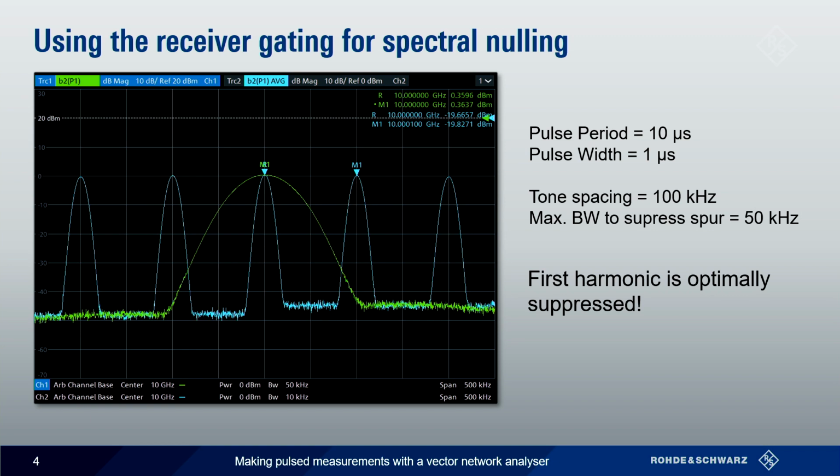So we can see each of the line spectra. The central component is the one that we want because this contains the information about the carrier frequency. And overlaid here, we can see what the filter shape of our network analyzer filter looks like. And in this particular example, we've got optimum filtering here of those adjacent side lobes.